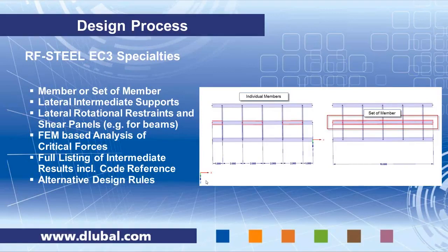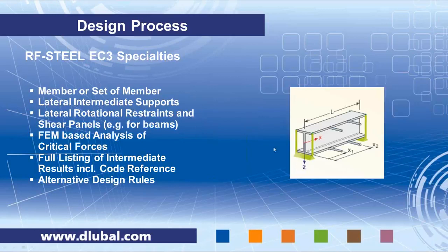When we think about buckling lengths, slenderness, loading, and also horizontal supports, it's clear that the length of a member is an important parameter for critical loads and critical moments, for example. We also can handle lateral intermediate supports in a very simple way. You don't have to divide members when you want to put a lateral support, for example, with a nodal support there. You can just assign the distance of a lateral intermediate support in the design module, and when we talk about critical loads and effective lengths, the software will take care of it, and it knows that there are those supports.